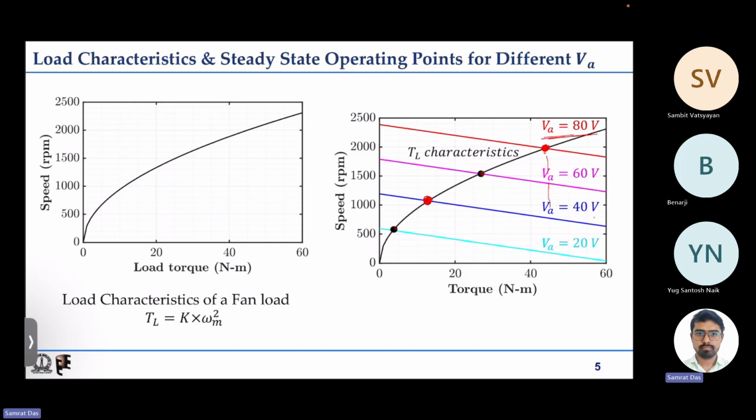And this information is actually useful if we want closed loop control. For closed loop control, we need to have the dynamic model of any system, so that we can do controller design, and that will enable us to control the dynamics. Say we want the speed to go from n1 to n2 within this much seconds with no overshoot. It should not go higher and then come back. It should go straight away like this.